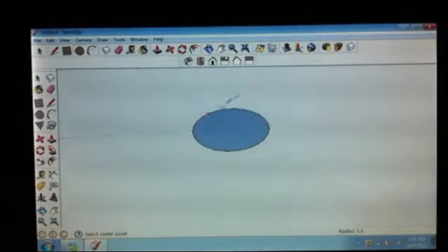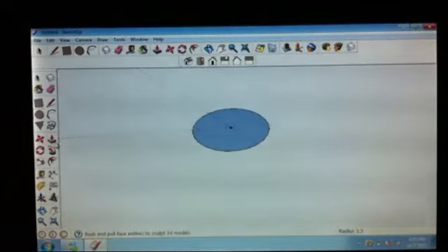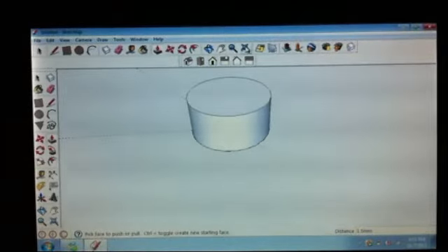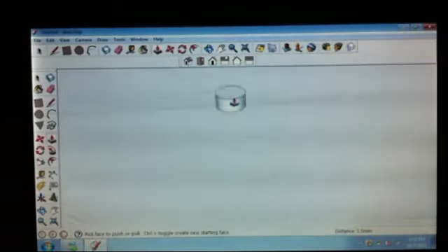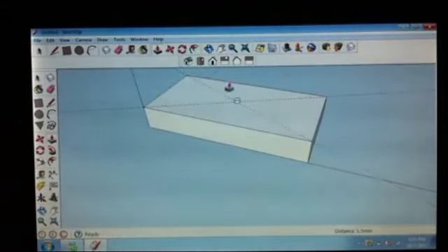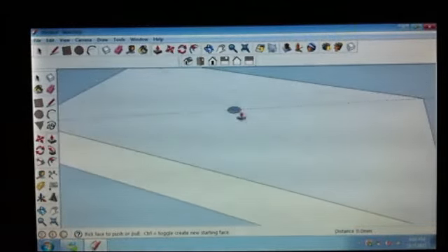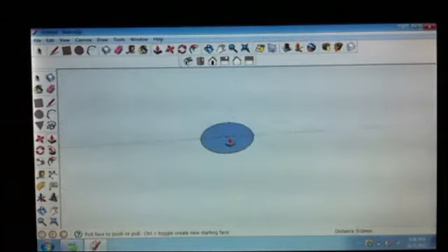It looks like actually that now the circle covers it. That's exactly the case because your rod is a tight fit onto the base. So now you are going to bring the rod out. I'm going to make this small now. I'm going to move the rod out. Sorry, let me undo it because I can actually state the length of the rod that I want.